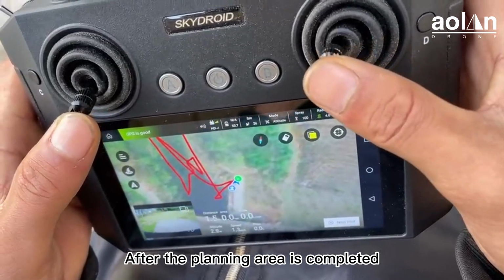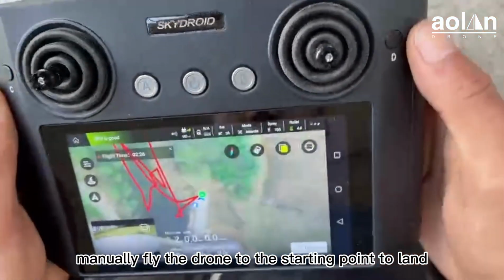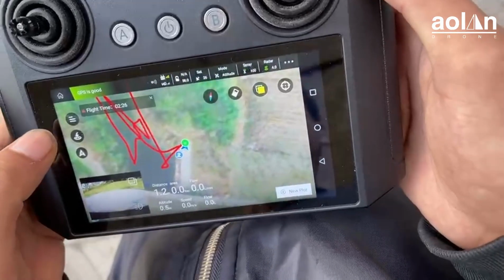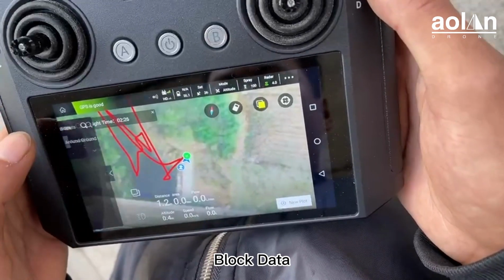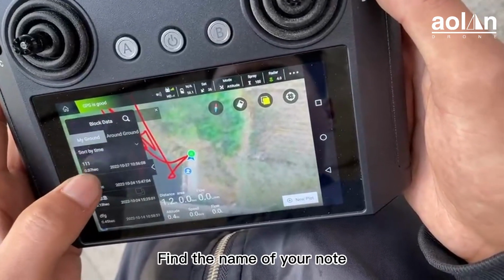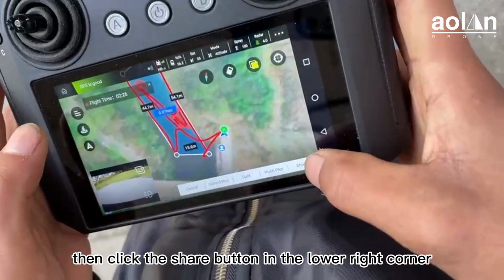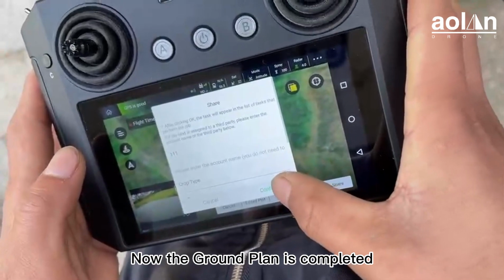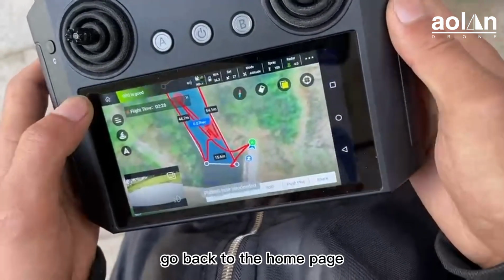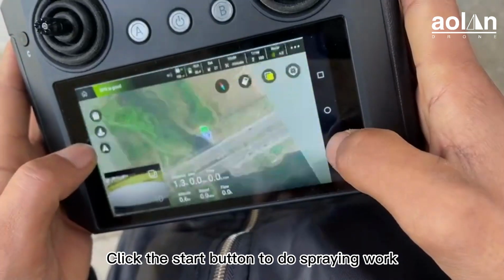After the planning area is completed, manually fly the drone to the starting point to land. Click the first button in the upper left corner, Block Data. Find the name of your node, then tick the Share button in the lower right corner and click Confirm. Now the ground plan is completed. Go back to the home page. Click the Start button to do spray work.